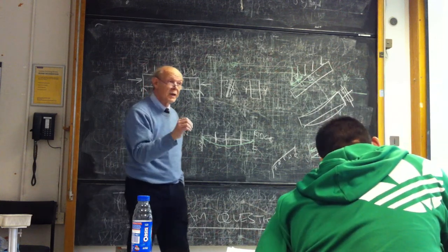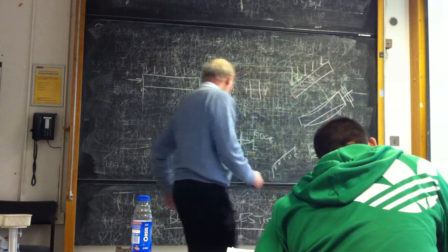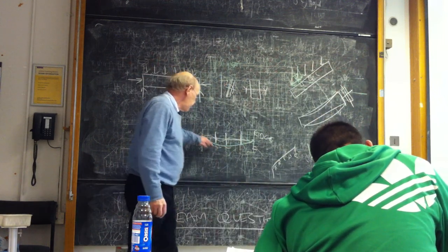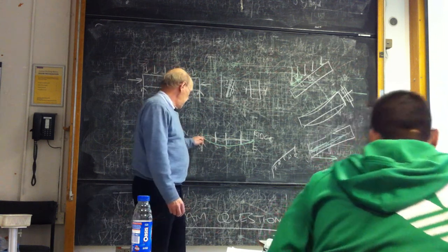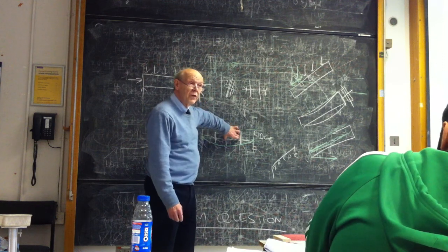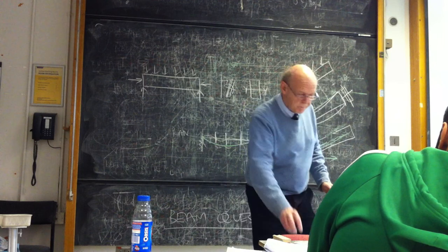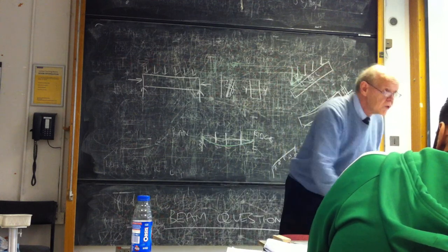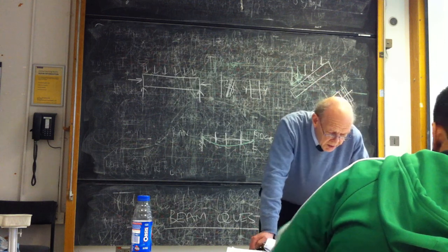So when you come to check the combined effects of bending and axial effects, lateral torsional buckling might be a problem because it's only restrained there and there. Straightforward Euler buckling probably won't be a problem because these are very short lengths. You can't really move sideways very efficiently. So again, there's a degree of engineering judgment involved in designing one of these things. So let's have a look and see where it takes you.